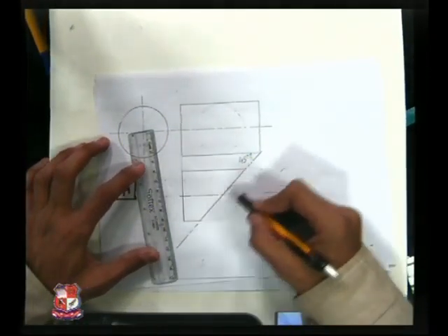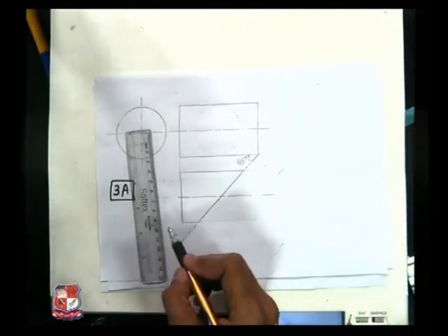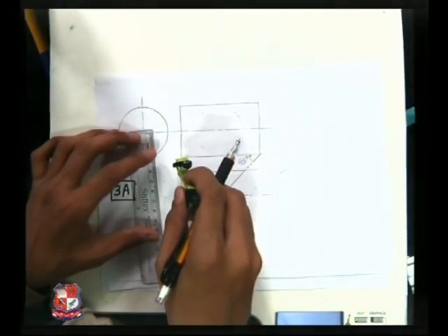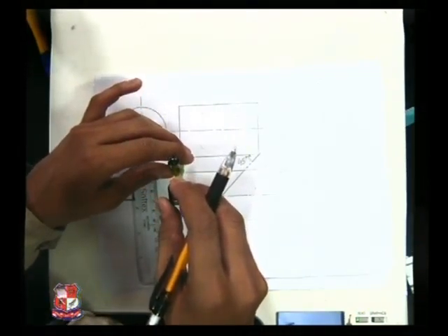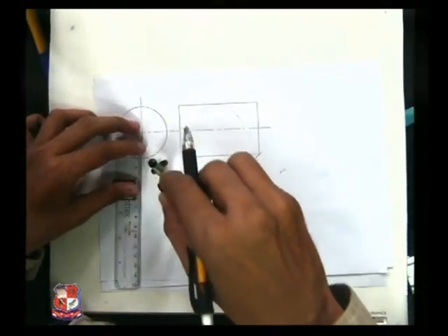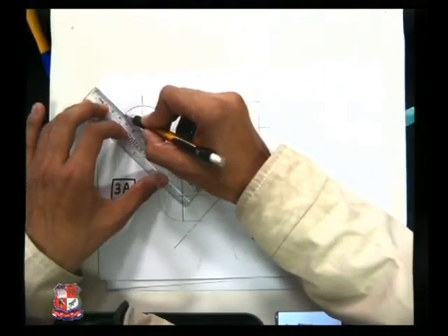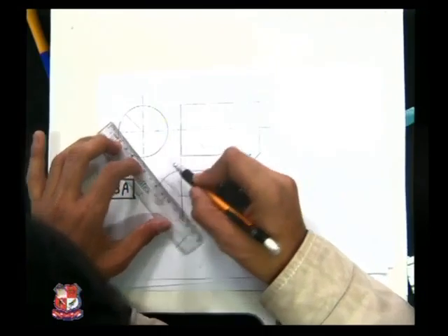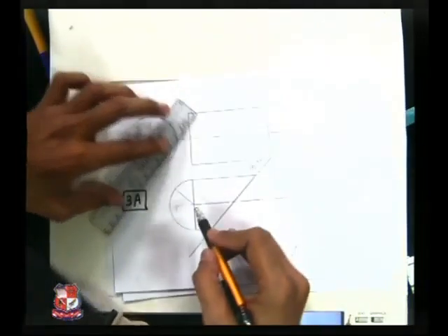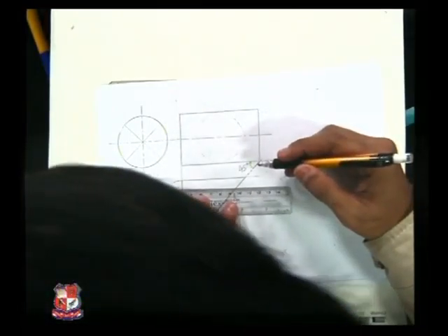If we cut the cylinder from here, what would be its front view? That we have to draw. So for that, again we have to draw imaginary generators over the periphery of the cylinder, and for that let me draw its side view or a semicircle to the left side just to find out the points, and divide this semicircle into 8 equal parts from here and here, and similarly from here, and draw these imaginary generators over the periphery of the cylinder like this.